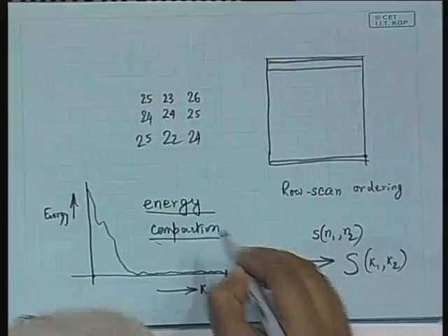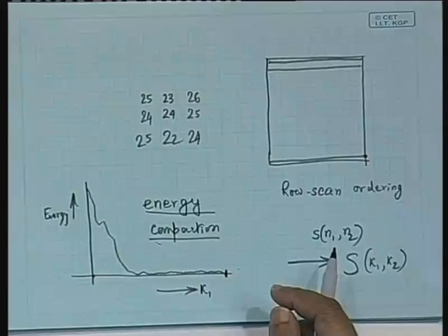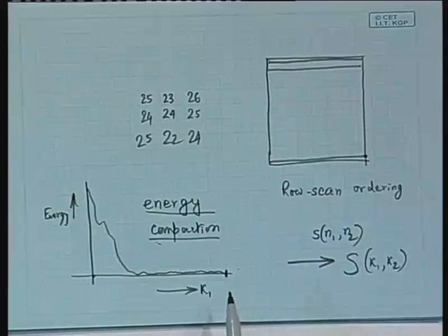So the transform that we are going to use should offer some energy compaction property. Energy compaction means that using only a few spectral coefficients, or only a few k1 coefficients, we should be able to have most of the energy. Let me give a typical example.